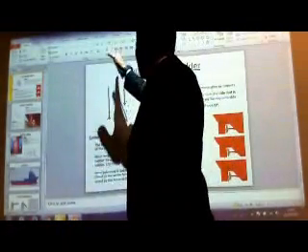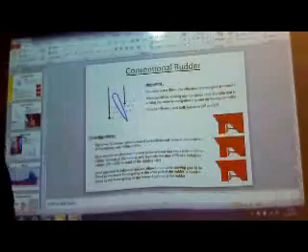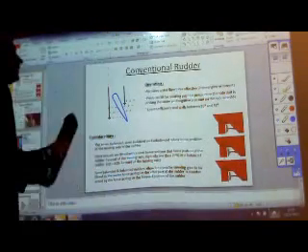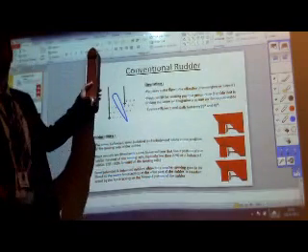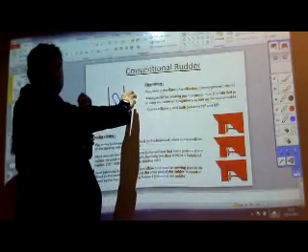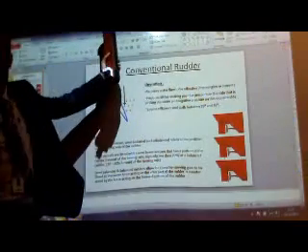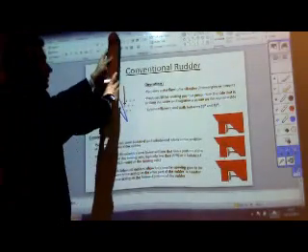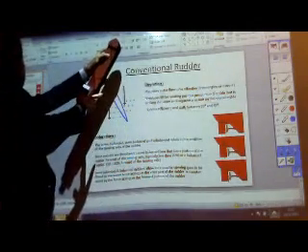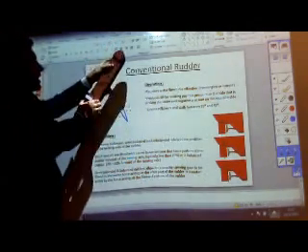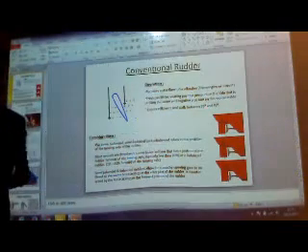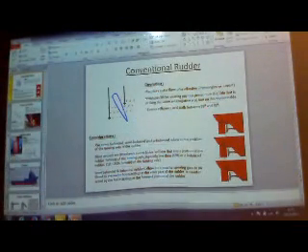So if this would be a ship here, and if this was the rudder, well then you have given a starboard rudder, starboard helm. What does this cause? A high pressure system around here and a low pressure system around here. So what will the ship try to do then? It will try to turn the stern of the ship towards the low pressure system, and it will eventually start turning your ship in the starboard direction. That is how it works. Make sense?